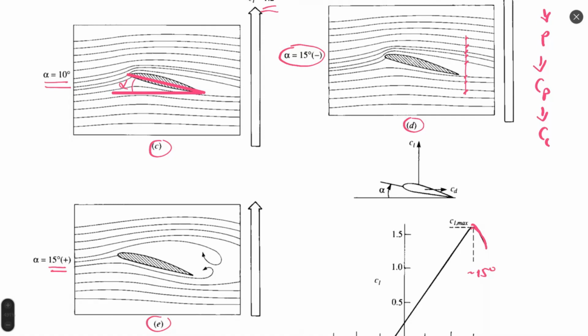Flow separation happens differently for different airfoils. For some airfoils, like thin airfoils, it might happen with such a rapid transition, right? In figure D, we have almost no flow separation. In figure E, we have huge flow separation the next moment. This is why thin airfoils are not always perfect for control of lift coefficient at high angles of attack. There is a big chance of flow separation.